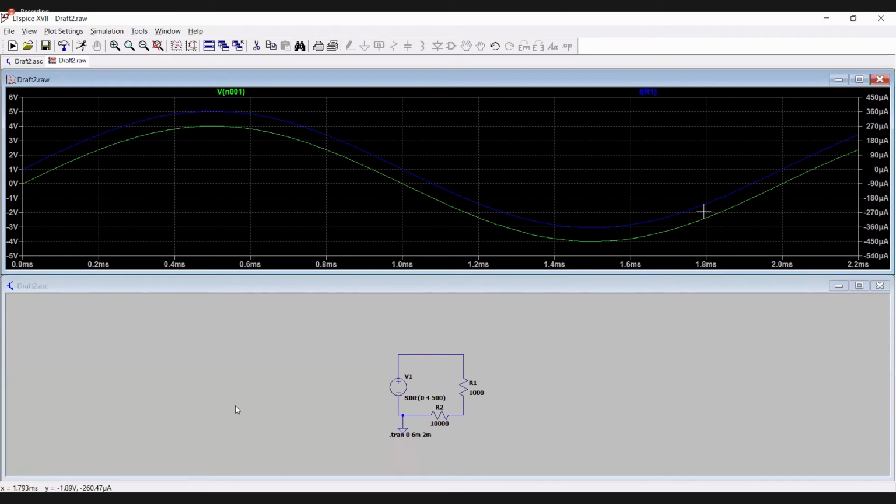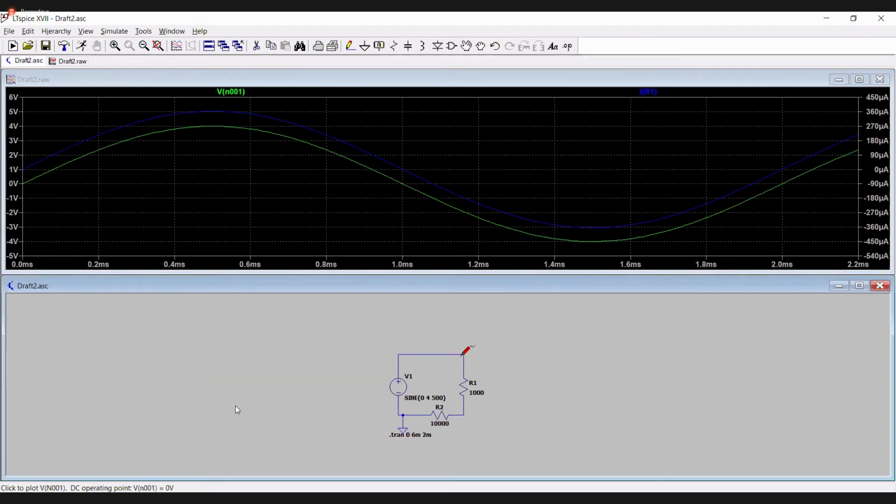Also, I have recently found a technique to measure the voltage. I saw one of the video lectures on YouTube, and I saw this one. This technique is used to measure the voltage across any element. In the past in DC, what I told you to do is to simply place your probe on two different nodes containing your component, and then subtract, di ba? Actually, there's a way to do that automatically here in LTspice.